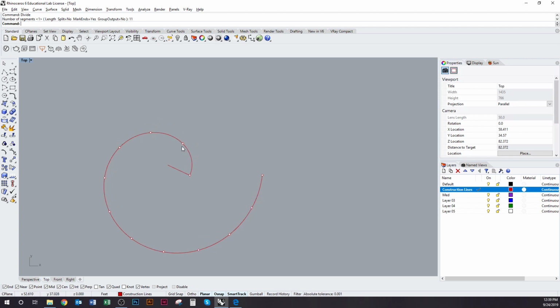Then what I could do is draw each line independently. So again, use the command line, option perpendicular. I'm actually going to draw something with different length lines at each point. So I started with 3, maybe I'll go 4, and then 5, getting longer.